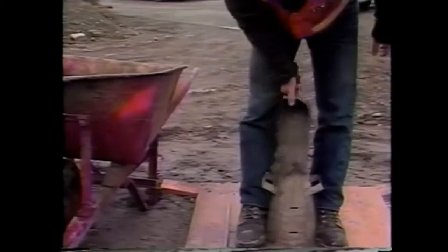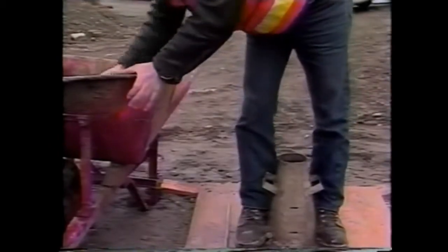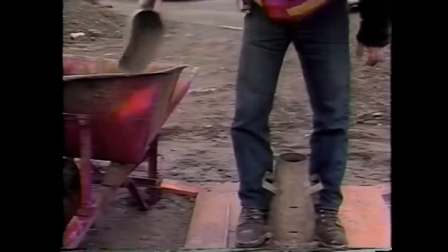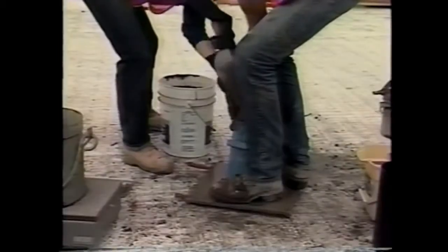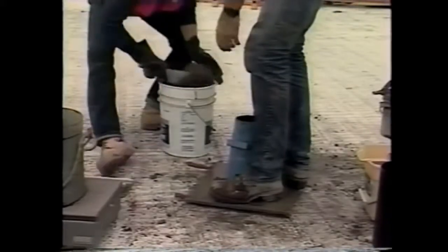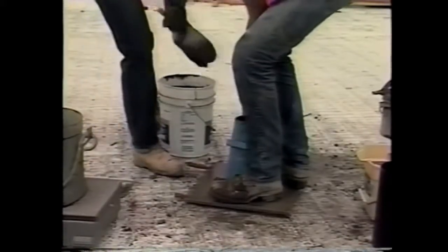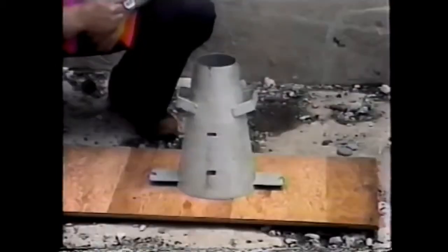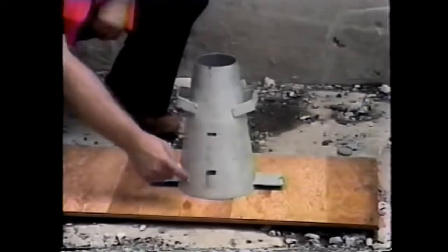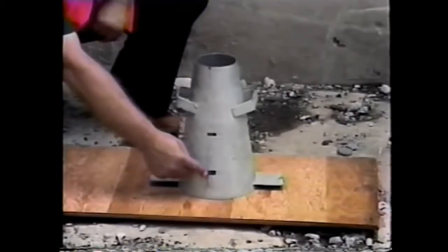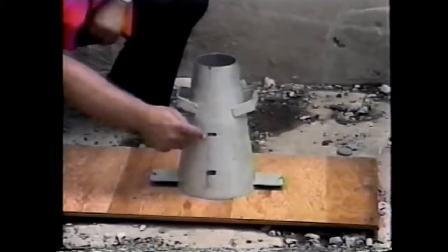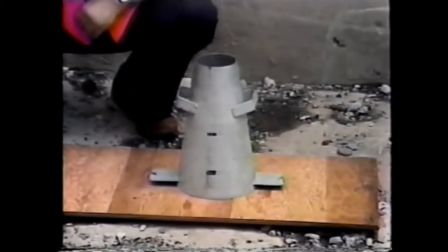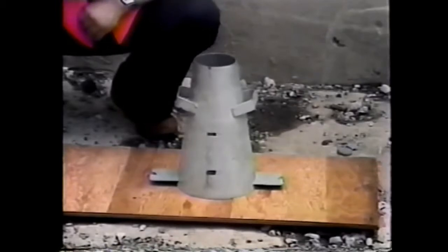The cone is filled by moving the scoop around the top to distribute the concrete as evenly as possible. The filling is done in 3 layers. Each layer should take up approximately 1/3 of the cone's volume. So the first layer should come up about 2.5 inches from the base. The second layer should come up about 6 inches. That's about halfway up the cone. And the third layer should overflow the cone.